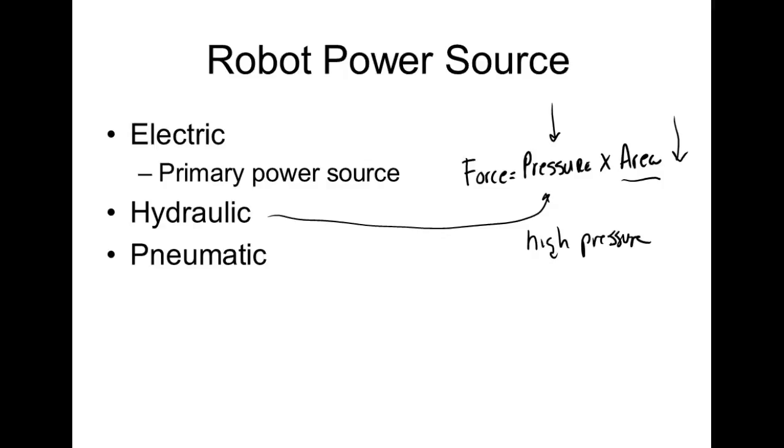Now the problem we have with pressurizing gases is when gases come under pressure, eventually they'll turn into a liquid. Y'all understand that? We buy liquid oxygen all the time. We buy CO2. We used to play paintball when we had our own field station. And if you're a welder, you go out and buy those gases. Those are all liquids. And how do they turn them into liquids? They just pressurize them. Another problem we have with air is that air itself carries a bunch of impurities. So normally before we run it in, we got to filter it. And then plus, air has a lot of moisture in it.